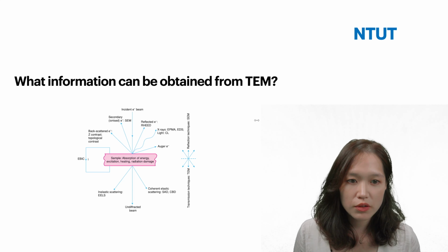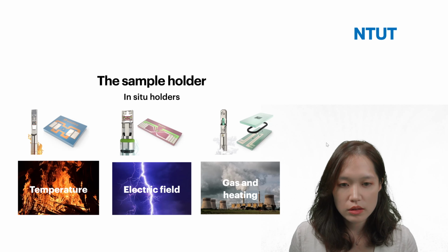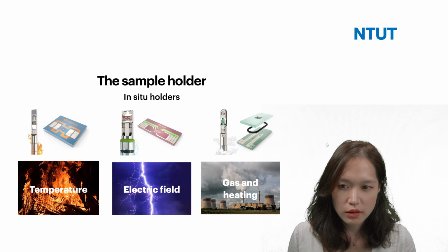For example, this is not very good for eutectic alloys. It is very important that your material does not form a eutectic alloy when you consider using a temperature type, because at high temperature, eutectic will melt, so the sample will either be deposited onto the holder itself, or even worse, it will be deposited onto the objective lens.